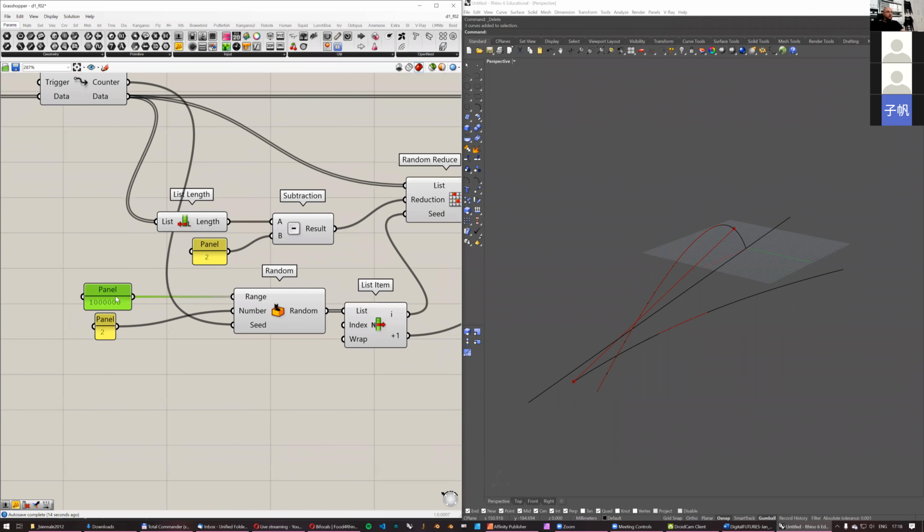Anyway, so the range here should have a domain as an input. A domain is actually a range. This is very misleading because Grasshopper is not strict with naming, because there's something called a range, and it's a completely different thing. But a domain is a range of numbers, and it defines values between these 2 numbers. So if I put a range here, it actually generates 2 random numbers between something and something. And instead of just defining a domain here, I defined a number.